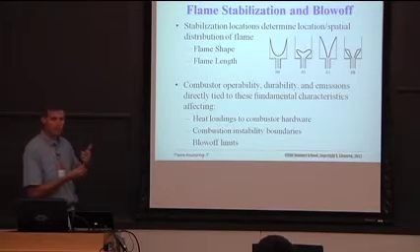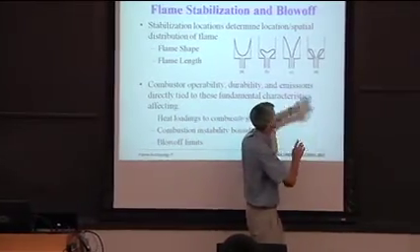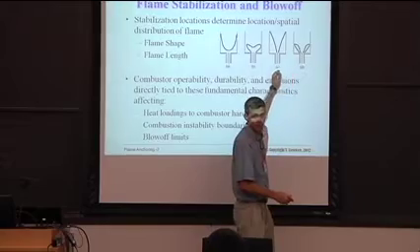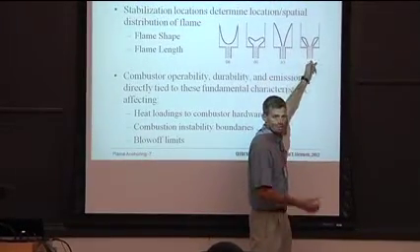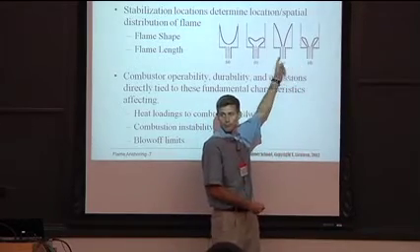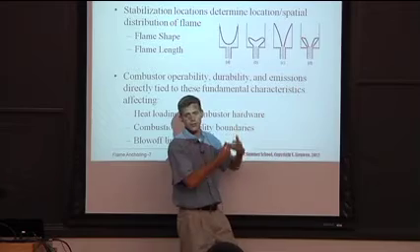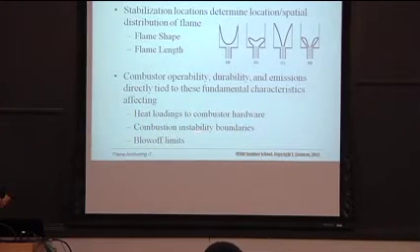But what happened is you had this hysteresis. So once you hit it, all of a sudden, Tim Lieuwen's hypothesis is they had an abrupt bifurcation of flame shape. So they're moving along, all of a sudden, pop, they hit this thing. So they'd say, oh, shoot, and back off their equivalence ratio, but you don't pop right back out of it. There's this hysteresis zone. And so, very interesting things on combustion instability limits. And then obviously, blow-off limits is effective when the flame can't find any stabilization locations. That's ultimately blow-off.